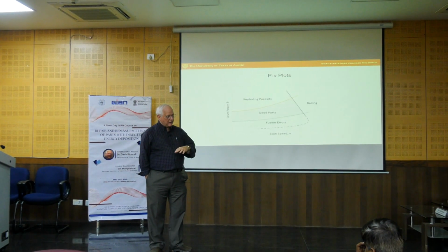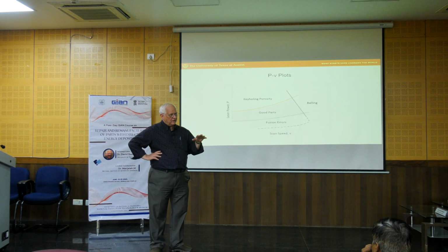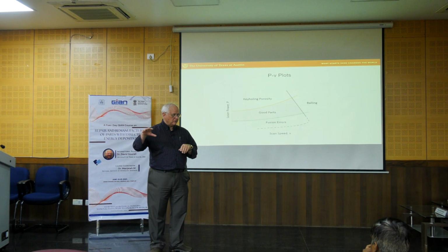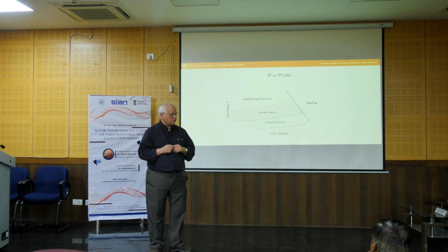Yeah, I think so. For me, first of all, the distinction between powder bed fusion and directed energy deposition, and again, this is very broad and very general, is that directed energy deposition can build with faster build rates, whereas powder bed fusion is perhaps best characterized by the finish and the accuracy of the geometry.